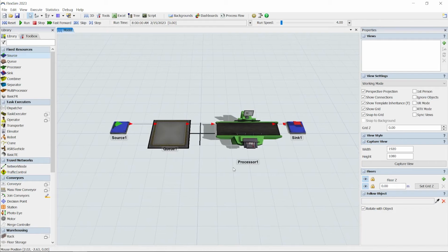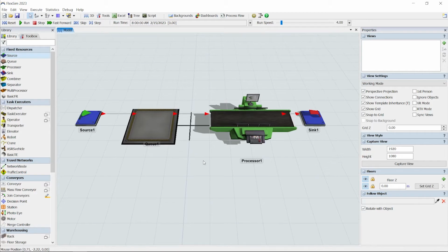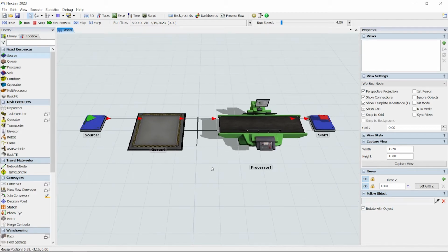One final thing before we run this simulation. For this example, we're building a model of a product testing system, and we need to have the right inputs to represent the system's behavior. Based on quick real-world observations, most products arrive for testing within 10 seconds of each other. There are also some outliers with 60 seconds or more between arrivals, bringing the average up to 15. The exponential probability distribution is FlexSim's default for these inter-arrival times, so we just need to edit the default value